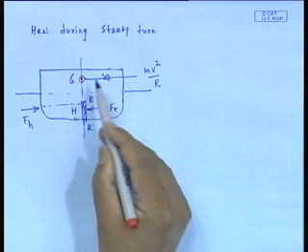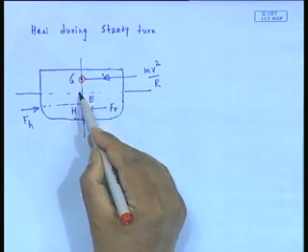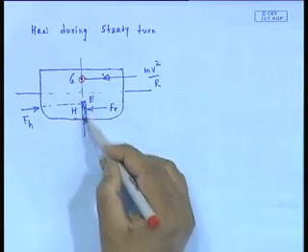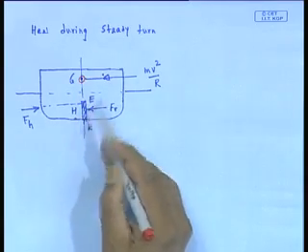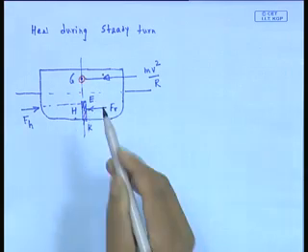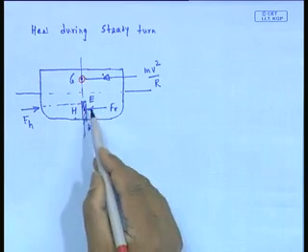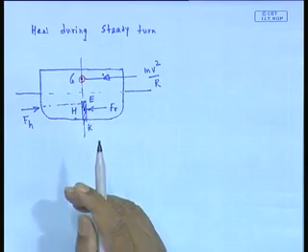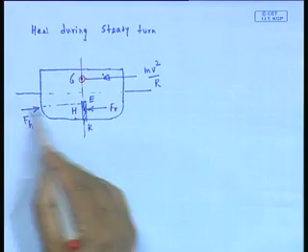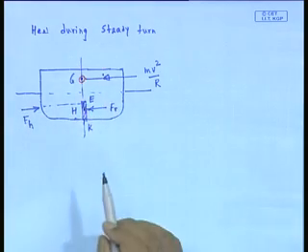For a typical ship we are talking, the center of gravity is normally slightly above that. If you call this the draft here, the rudder is somewhere approximately around the draft. The middle of that rudder, let me call this H, is the point where the rudder force acts, the resultant rudder force approximately, and FH is acting, let us say, at a point E.